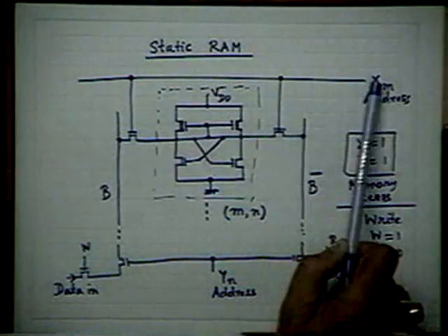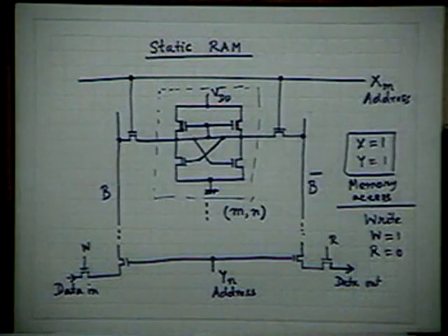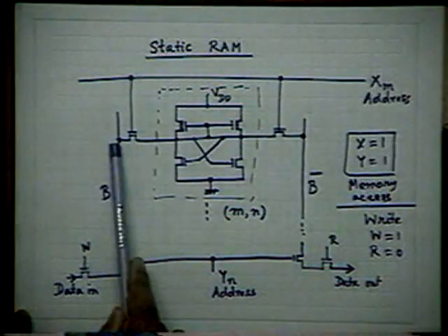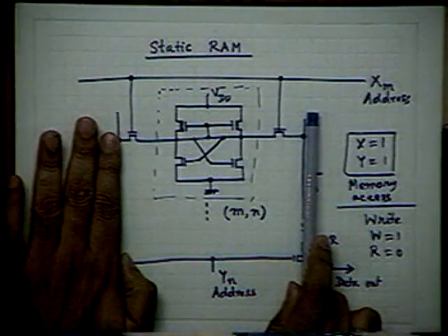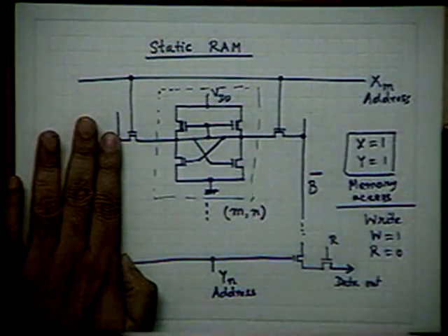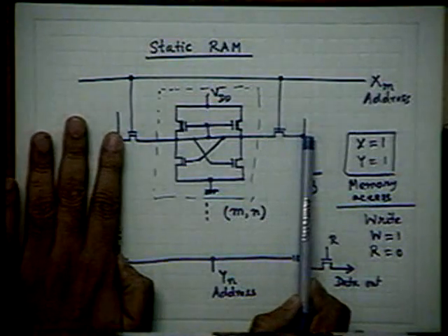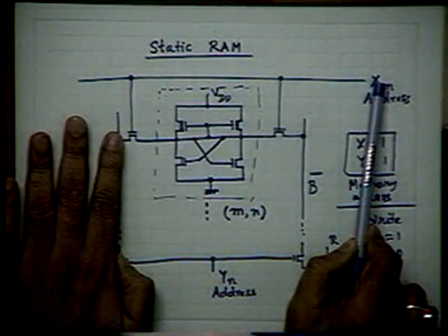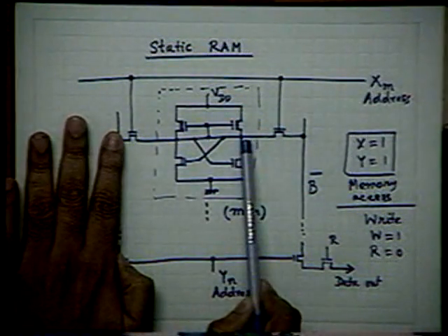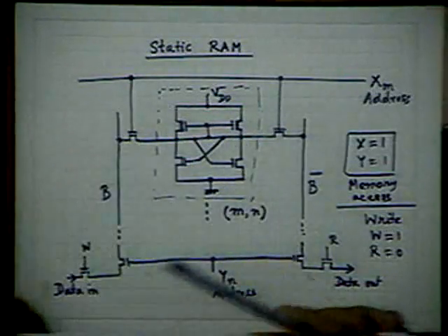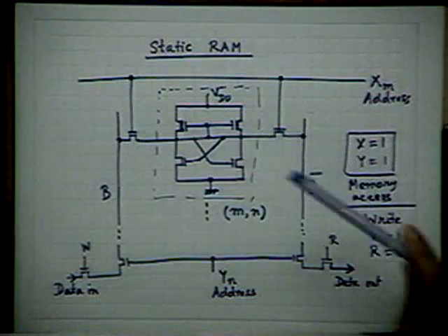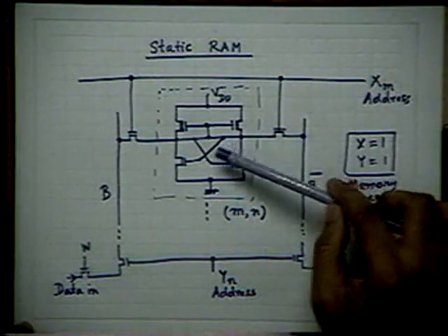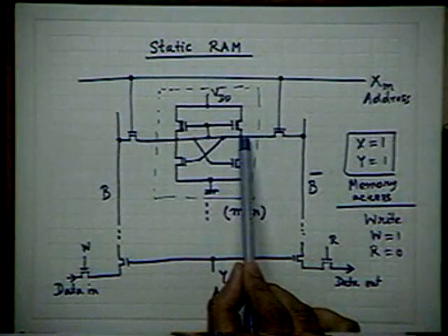Then you see that you turn on XM1. I have applied 1 here, and by that time it has been established. I have given sufficient time for XM. Let us assume that this 1, 0 is established properly. Then you are now switching, and this XM is turned on. Maybe it was 0, 1 in the earlier state. Again, there is a finite time involved; this 0 to 1 switching will not be instantaneous. Then this will become 1 and this will become 0.